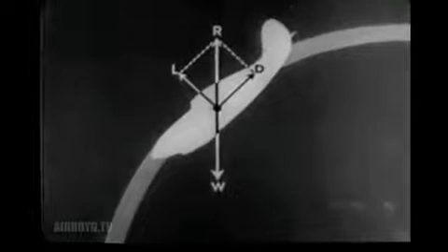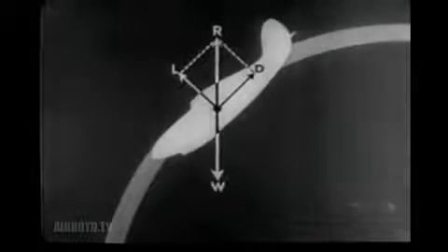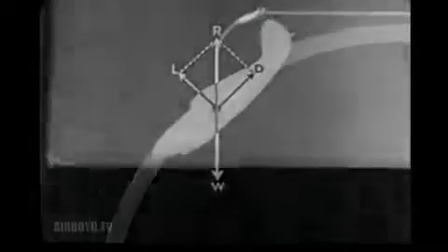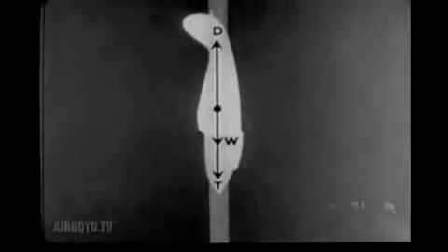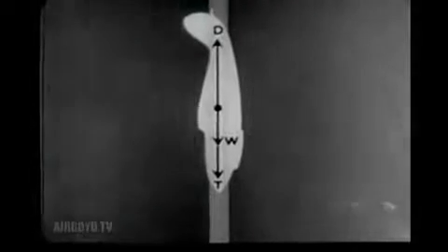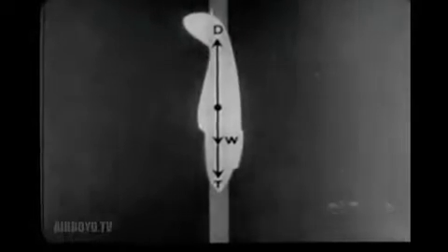increases. Lift decreases, since in this attitude the weight of the airplane is opposed by the resultant of lift and drag. As the flight approaches the vertical, speed increases until the terminal velocity is reached in the so-called vertical dive. In this condition, lift is 0, and the weight of the airplane plus its thrust are opposed by drag alone.